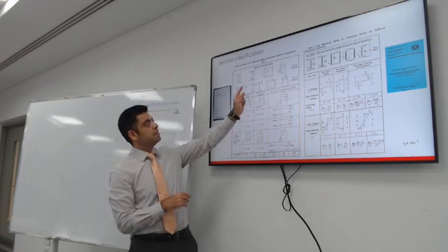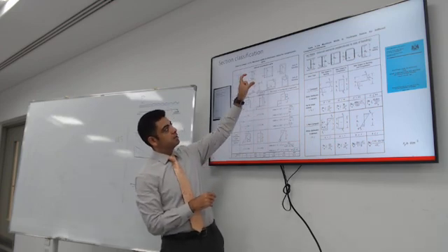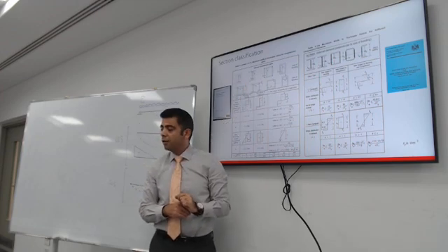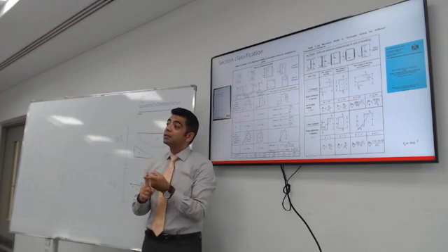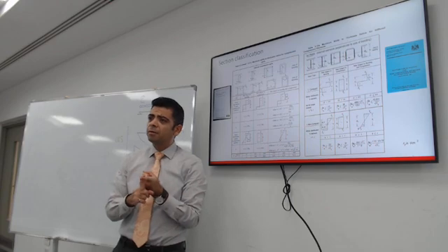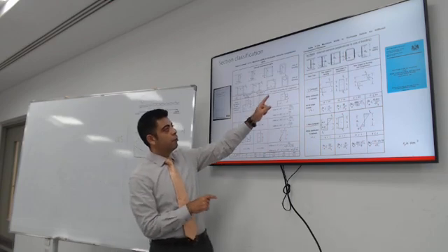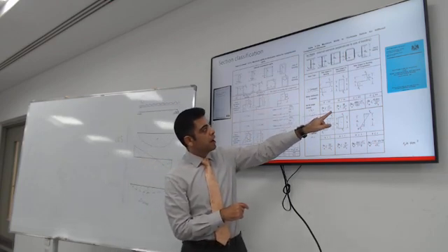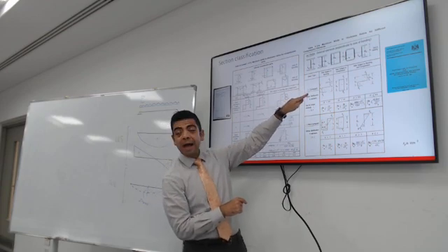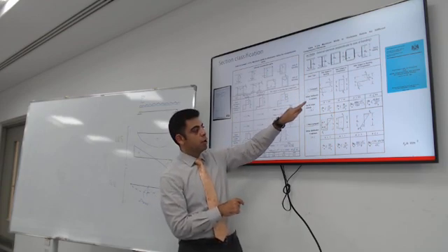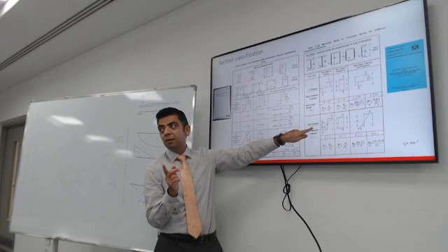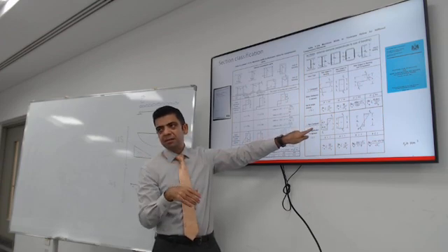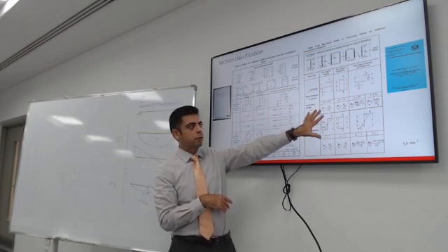You will look specifically at the dimensions of the section and the yield strength of the material, and follow these formulas that will tell you if this is a compact or class 1 section, or is it non-compact, or class 2, or a flimsy section. That's the terminology for the Egyptian code.